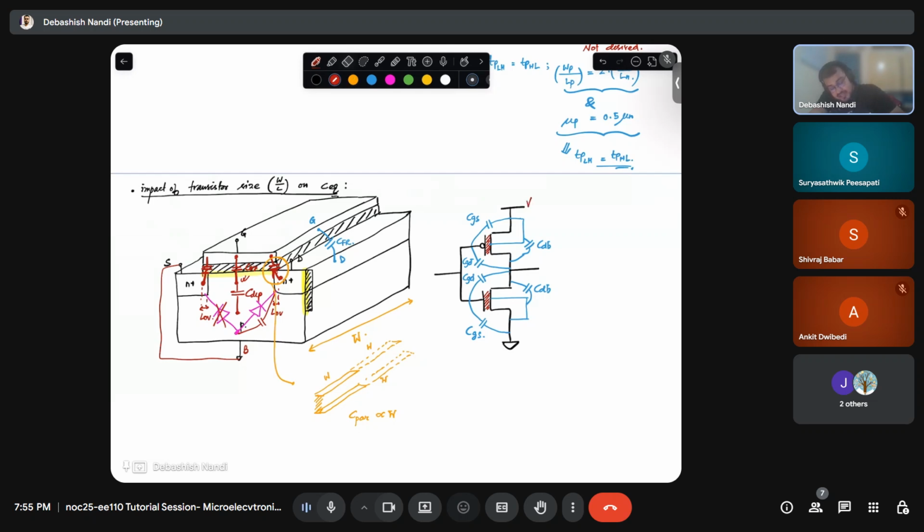Now, in small signal sense, what is VDD? It is ground, right? So can I model my transistor inverter parasitic capacitances like this? So I will have a capacitance to ground, this drain to ground, and also this drain to ground.